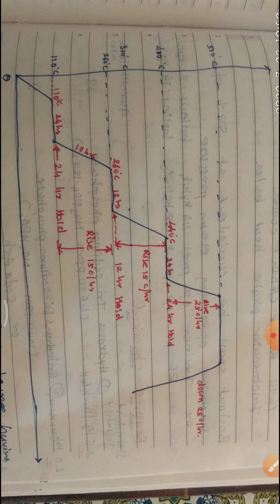During this temperature increase, maintain the vessel boiler pressure at 22 bar. When it reaches 22 bar, and if it goes above 22, then open the vent and maintain the pressure by opening and closing the vent, and start our boil out at 22 bar.